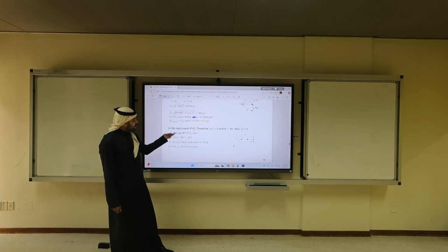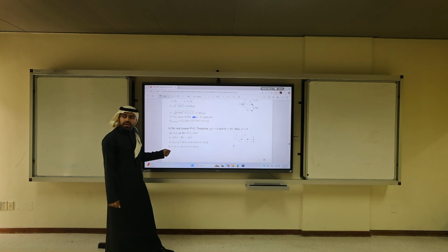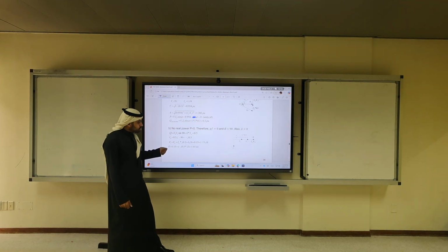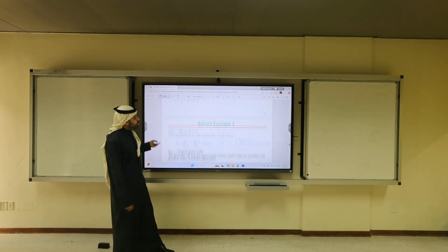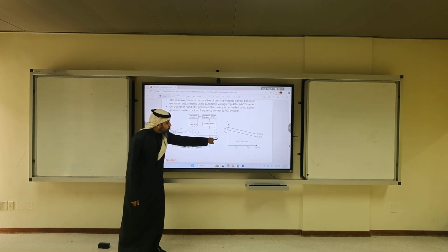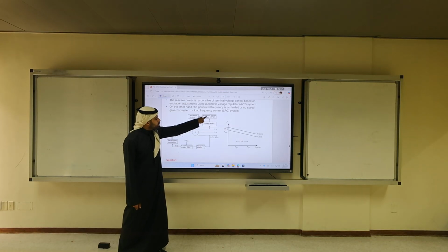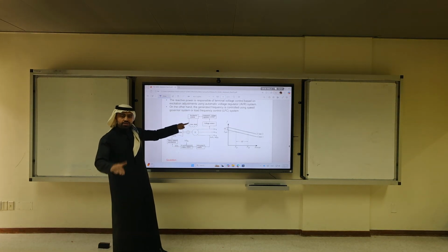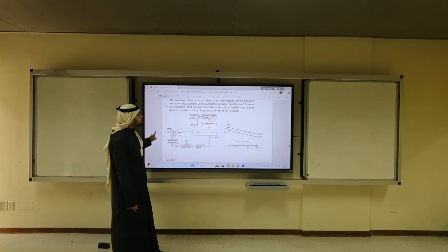Well, we do the measurements in P, we do the measurements in Q, and we noticed that Vt would increase, so we increase the voltage. So we send the signal to the exciter to increase E. Why? To deliver the needed Q that went from 0.3 to 0.5. So that's why in this diagram, we always monitor the change of P, the change of Q, and the voltage. With all this information, the voltage sensor adjusts the controller such that we increase the exciter or even decrease it. But that's not only the case, we also need to look at the frequency.